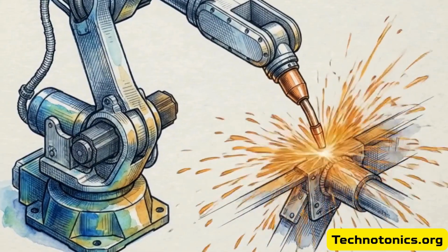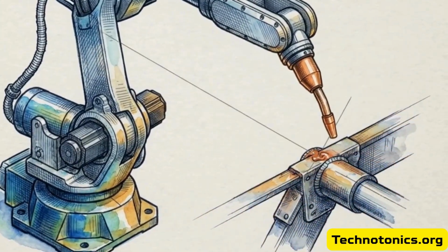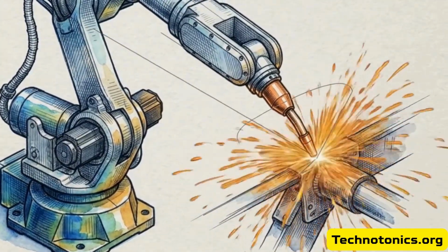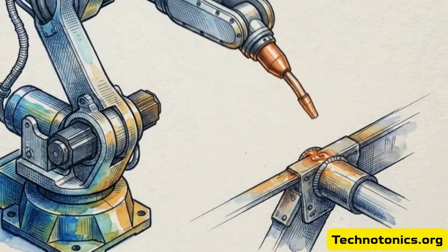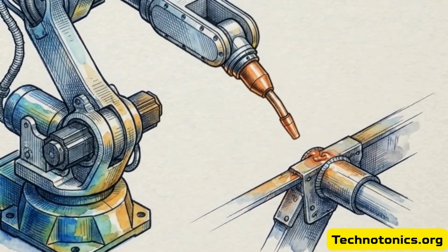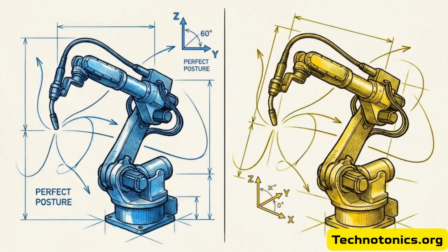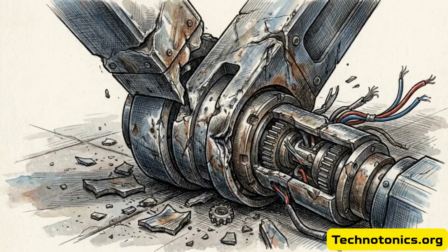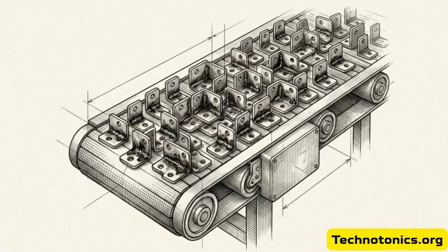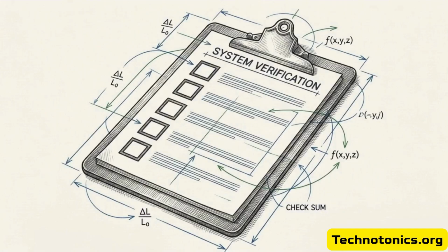When offline programming is done correctly, you get this: a massive industrial robot operating at top speed, executing complex tasks without a second of hesitation. It saves countless hours on the factory floor. But if the virtual environment doesn't perfectly match the physical reality, the results are expensive. A slight misalignment in your software can lead to hardware crashes, destroyed end effectors, or entire batches of defective parts.